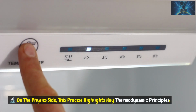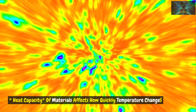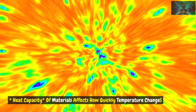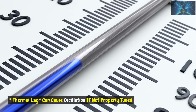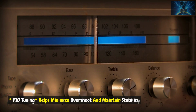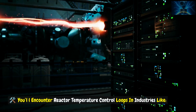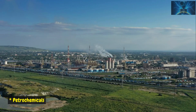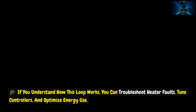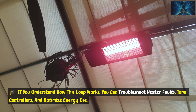On the physics side, this process highlights key thermodynamic principles. Heat capacity of materials affects how quickly temperature changes. Thermal lag can cause oscillation if not properly tuned. PID tuning helps minimize overshoot and maintain stability. You'll encounter reactor temperature control loops in industries like pharmaceuticals, plastics and polymers, petrochemicals, food processing. If you understand how this loop works, you can troubleshoot heater faults, tune controllers, and optimize energy use.